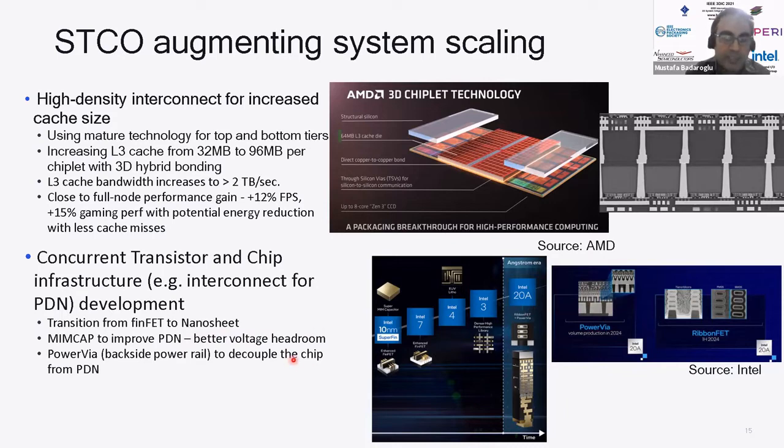So that's basically coupling this PDN problem that I mentioned before, the high interconnect resistance problem, and also improving the density of the chip, because you now have less routing in the front side of the chip when you deliver the power from the backside. So these kinds of innovations are now introduced at the device scale, which is actually making the 2D device 3D compliant, and is an enabler for scaling.